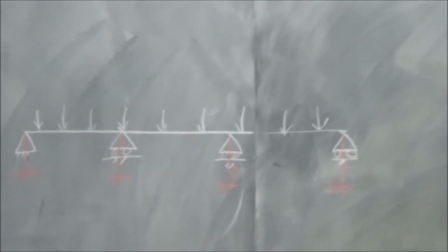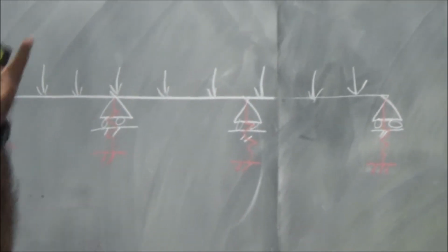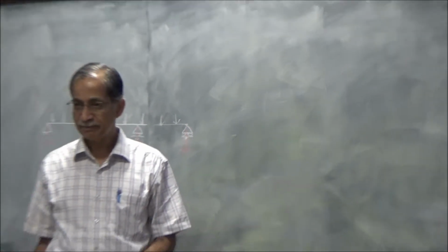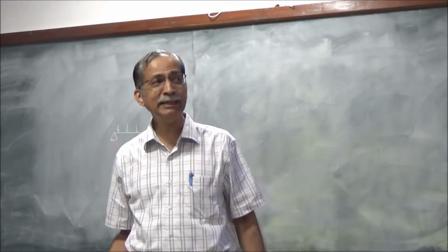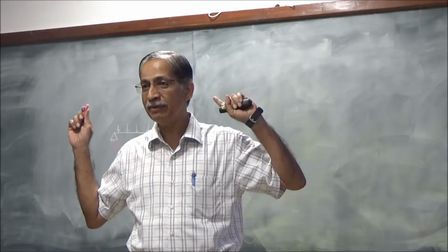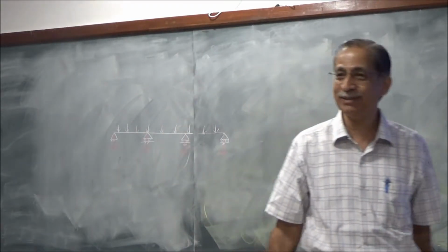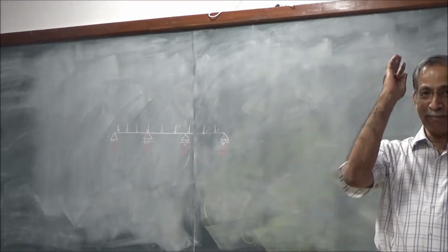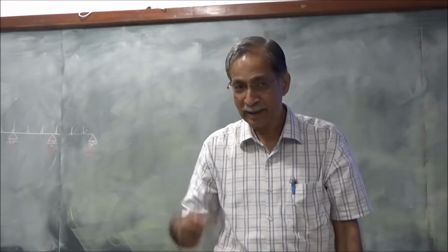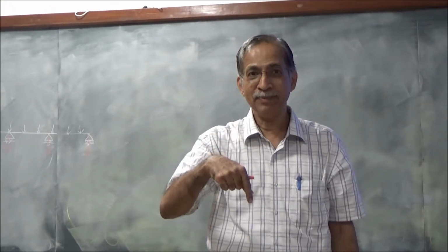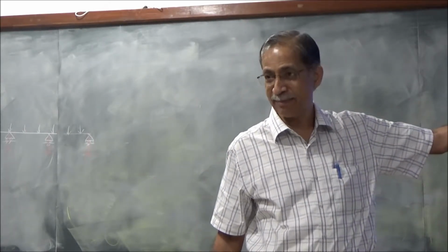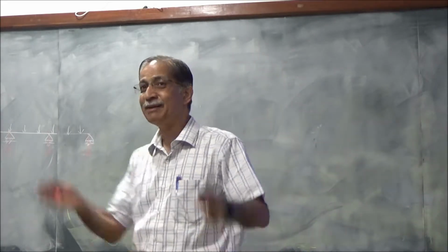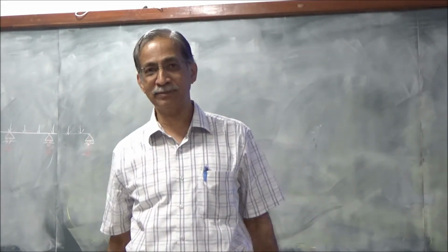Because this can handle any degree of flexibility. You understand what I'm saying? The beam is flexible. And interestingly, whatever size of beam you give, it depends on where you're cutting that 1 meter strip. If you are taking that 1 meter strip in the middle region, then the beam is more flexible there. If I'm taking at the extreme end region, it's not going to deflect much, it's more rigid there. So even the spring stiffness depends on where you're taking that 1 meter section. Agreed?